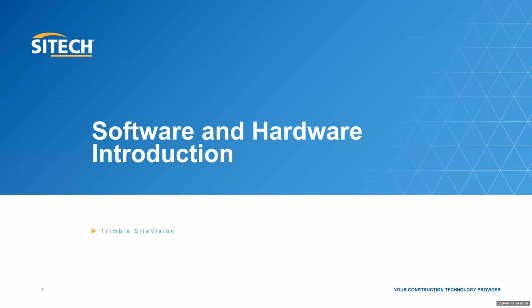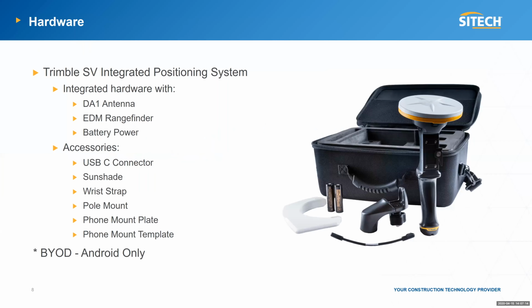So a bit of the software and hardware of SiteVision. If you would purchase a SiteVision kit from your dealer, you would get this bag where you would find a DA1 antenna, which you see on top of the holder, an EDM range finder. So you would basically be able to measure with your EDM some distances and points. And the battery power. You'd have these two batteries, and one battery would last around 2.5 hours. So you have two in the kit.